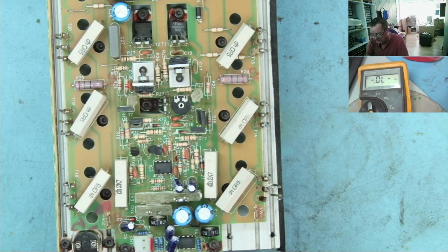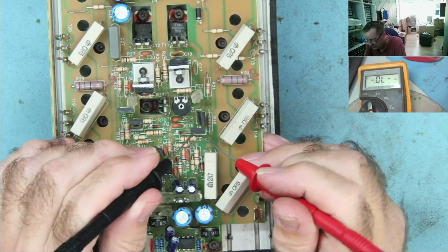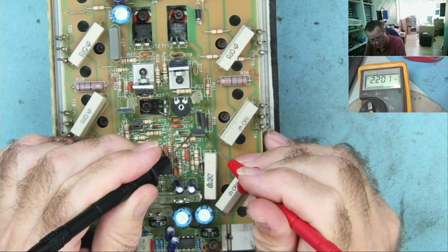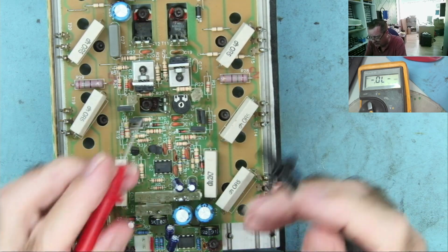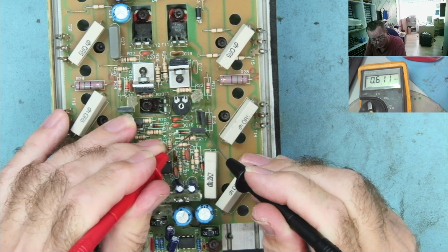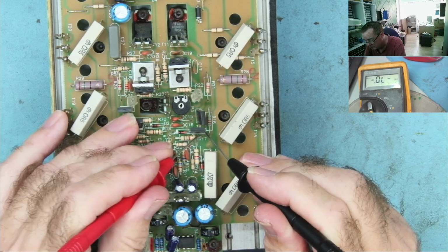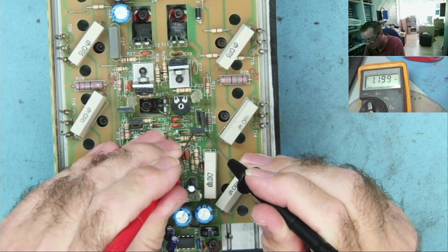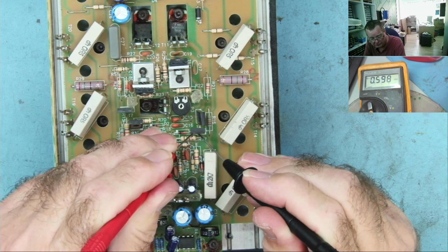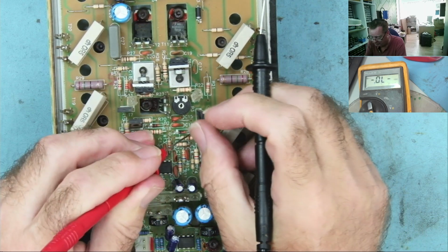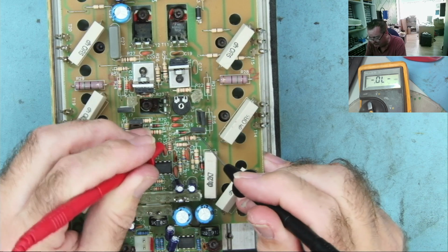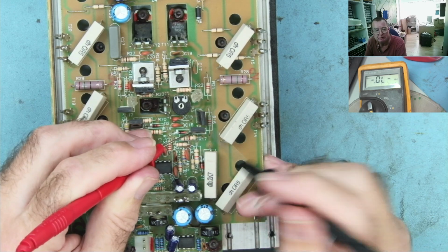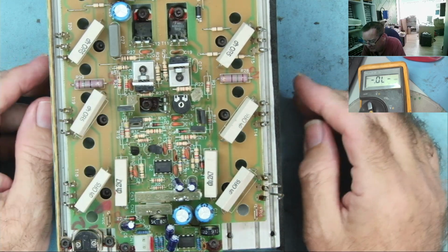Try another one over this side. Let's have a look. Is this the same device? Well, that reads open. That reads pretty much open. Let's go the other way. Junction. Open. Junction. Junction. Okay, so this end is the positive. This must be NPN if it's a transistor. 598, 611, base collector emitter, NPN. So that's how we can measure some of these.